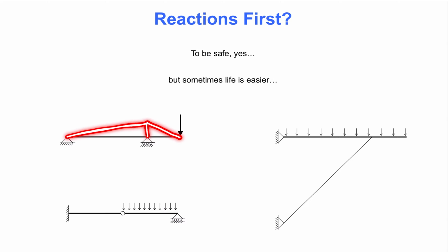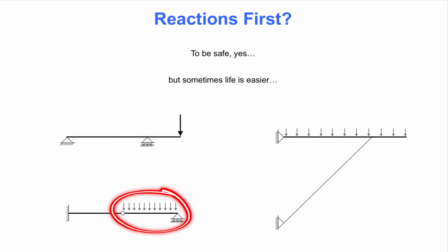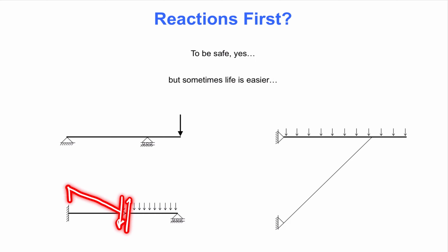For the beam below, we recognize the portion that carries the distributed load as a simply supported beam, carried at the roller support on the right-hand side and carried by the adjacent beam at the hinge. For that reason, we already know the bending moment of the beam that carries load to be the parabola seen earlier for the simply supported beam with uniformly distributed load. The remainder of this structure is essentially a cantilevered beam with a point load at the tip. That point load is the shear force at the end of the simply supported beam, namely QL/2.